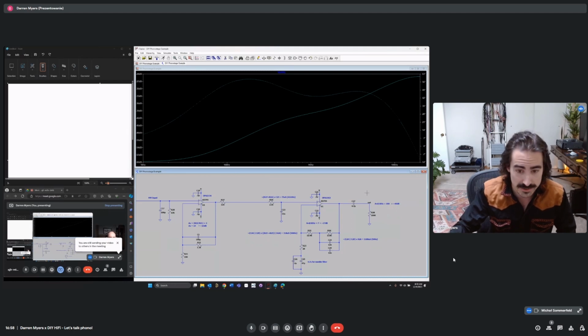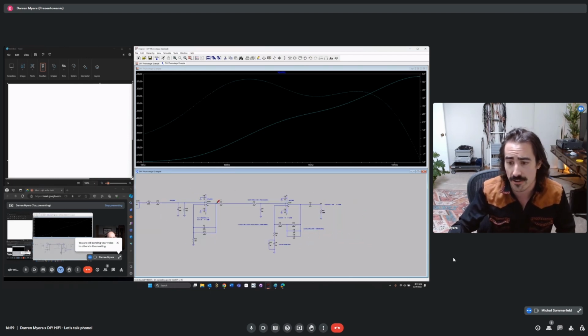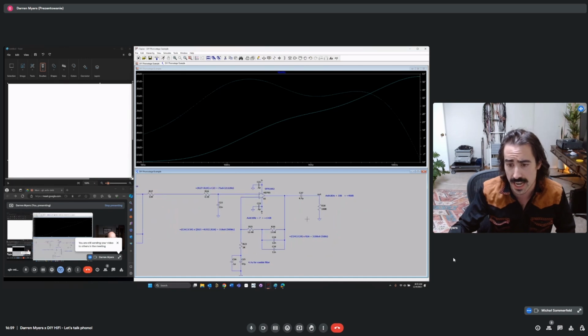We have 60 dB of gain, right? Because that's at 1 kilohertz, and we're down 20 dB more. And so we have to actually boost that up. Even an MM stage has 60, and then a moving coil stage has 80. So it really adds up quickly. So we have to be careful when it comes to the DC gain.